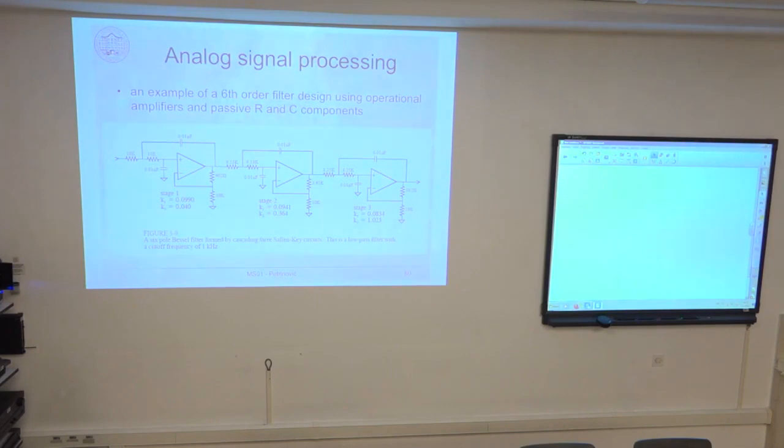It depends on the temperature range that this component was exposed to, so it has some kind of maturing, and the resistor will change its resistance. How much? Maybe a few percent. It is given in some kind of simulation tables. They also have this specification: what is the change of the resistance due to aging? You have to take this into account when designing such circuits, because otherwise you don't know what will happen after